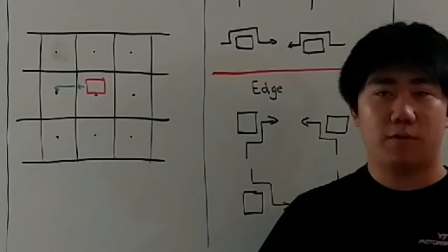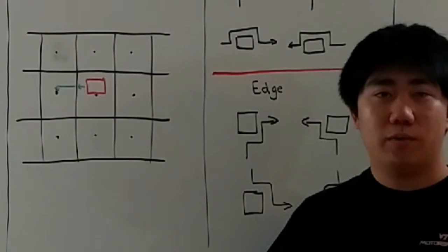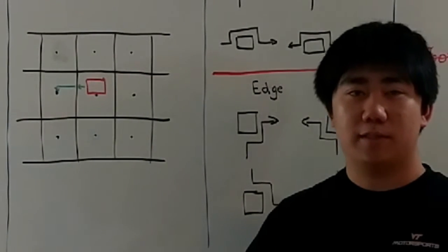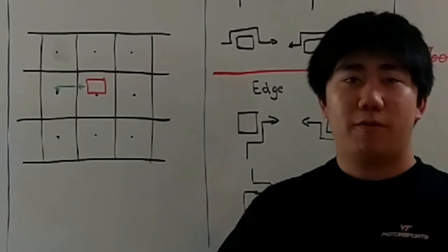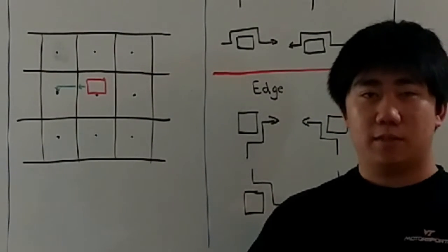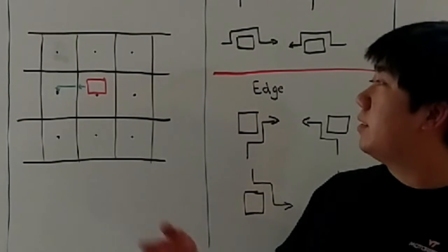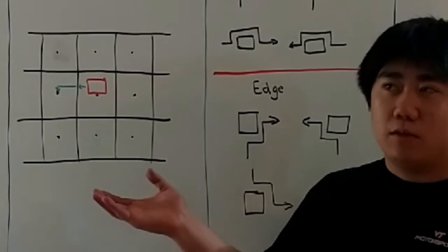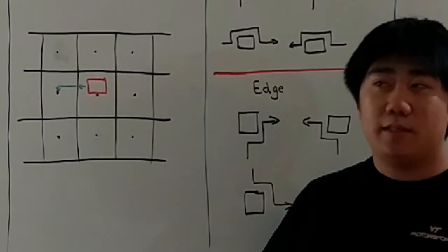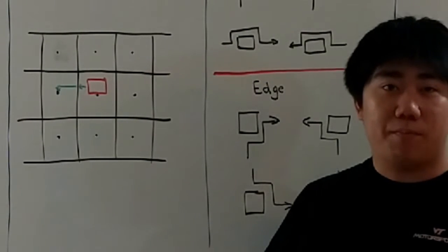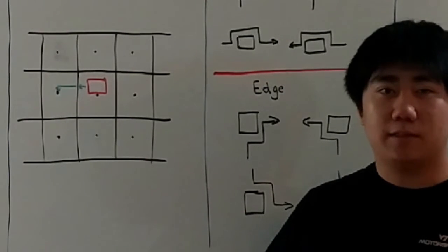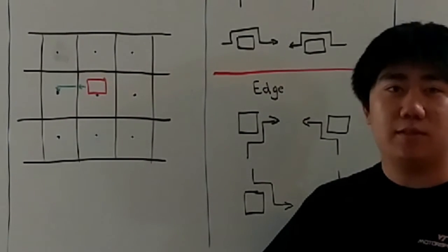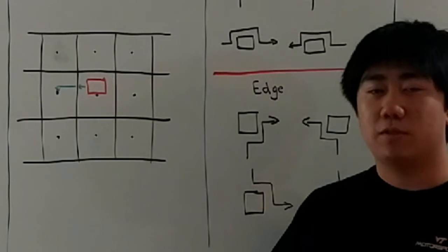In terms of the rover, we know that the rover may not always go exactly where it is intended to go. For example, the rover may only go 5 inches when it was expected to go 6 inches. So with this diagram, you can see that what the coordinator does is it builds a set of commands to get the rover to both move and to reorient itself by turning in order to get to the ideal waypoint that it was supposed to go to.